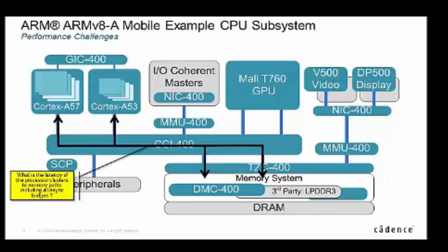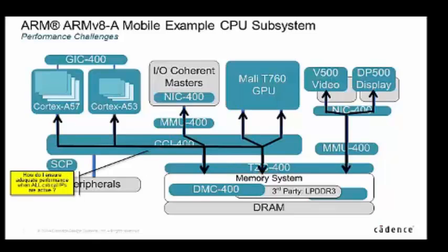If you're familiar with the AXI protocols from ARM, they allow multiple transactions to be in flight at any time from one initiating master. Obviously, the more you have in flight, the more hardware you have to configure to store all of that. So when you configure the interconnects with Amba Designer, you actually say, I want to support 32 outstanding reads and 16 outstanding writes, whatever. You configure it, but it's real hardware you're changing the size of when you do that configuration. How do you know whether you've over-engineered or under-engineered that?